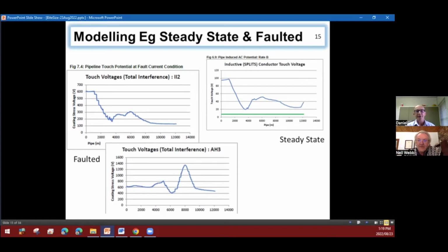The first step is to analyze the electrical system, and it's quite a complex issue to do due to the number of variable inputs that we have. The calculations are complex, and we use computer programs to do this. The vast amount of variable inputs take time to obtain. For instance, we need to determine the power line system. We need to obtain steady state load values, power line fault values. These we get from the power line operator.